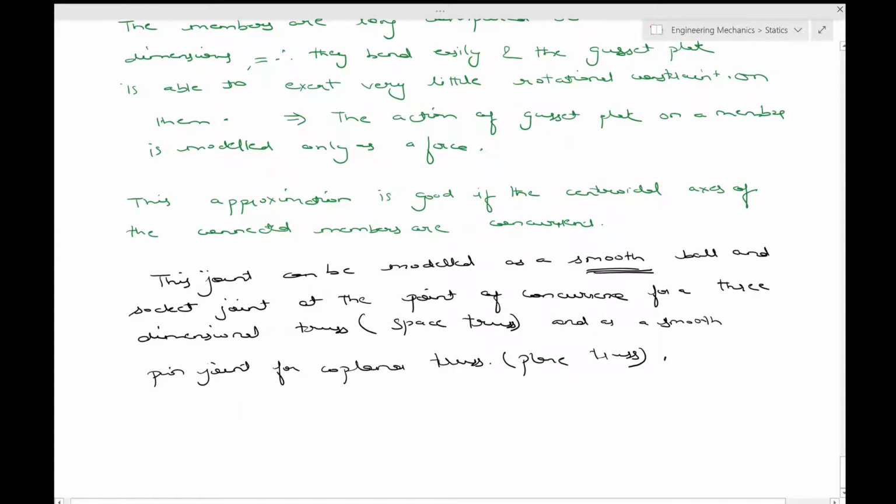Now, what are the external loads on the truss other than the weight? Okay, so the external loads on the truss other than its self weight are transmitted to the joints by a system of floor beams and stringers, such that the transmitted loads have very small moments about the joints.